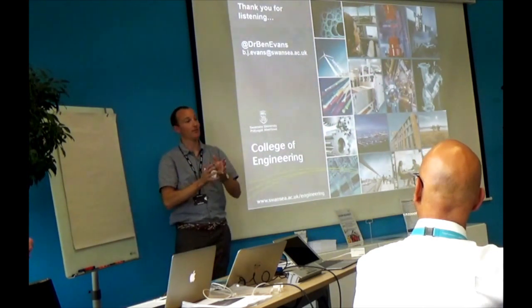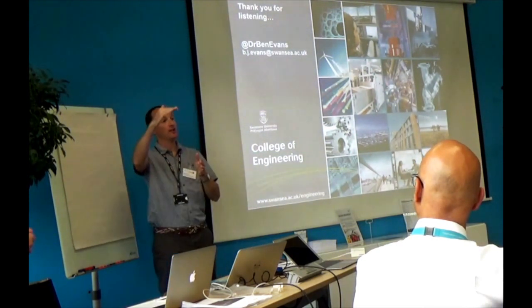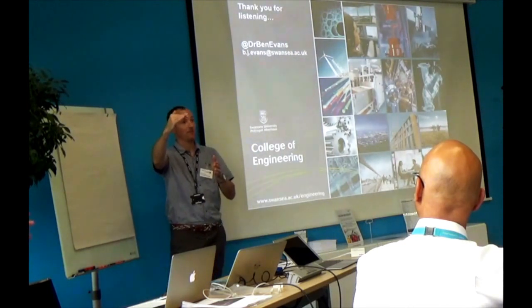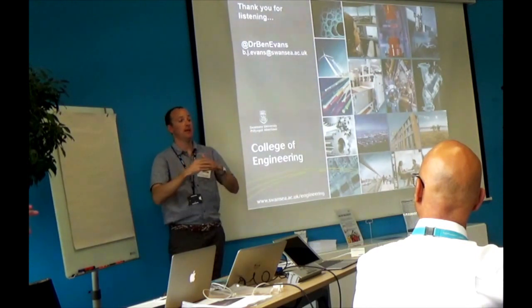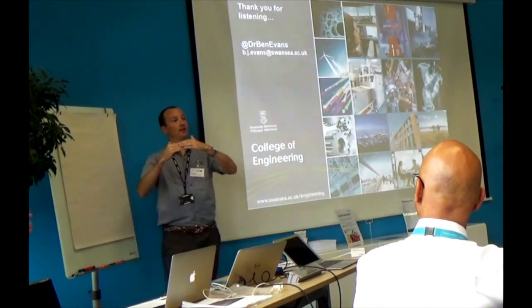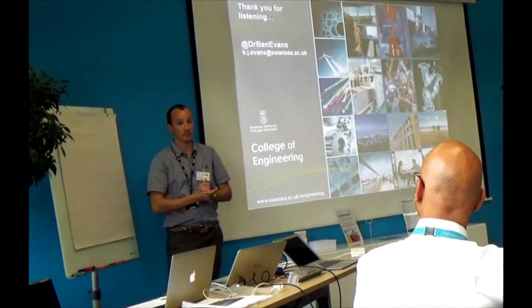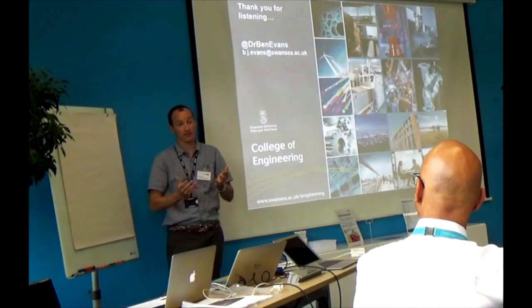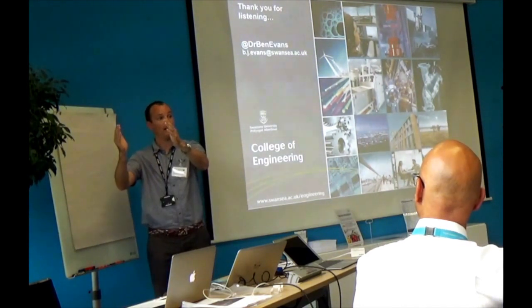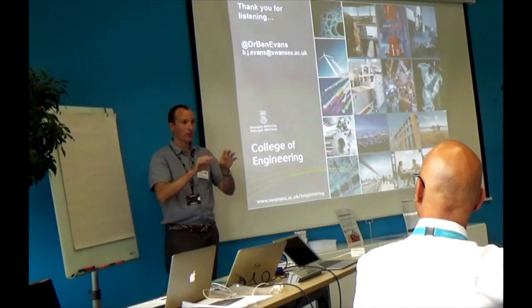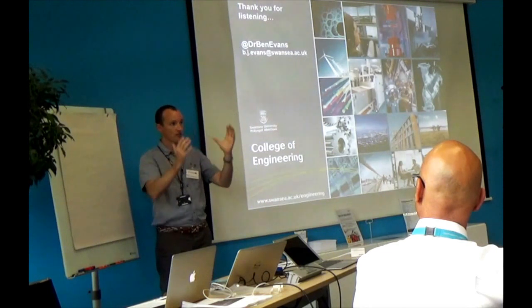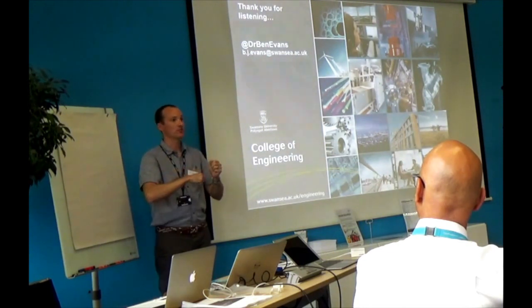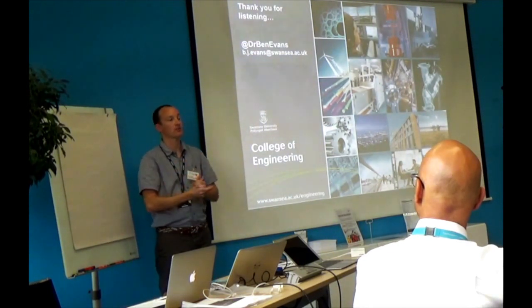Or if the optimizer is moving towards the boundary of the design space, and it seems to want to go outside of the predefined design space, in principle, you could in real time just extend the size of the design space and say, okay, if the optimizer wants to go there, let's see what happens if it does go there. So those are the kind of things we're playing with at the moment: real-time changes of the design space, adding in, taking out degrees of freedom in the geometric descriptions.